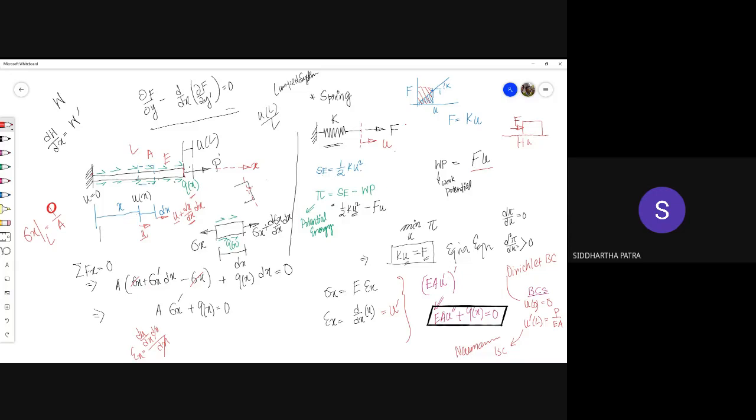When we are dealing with statically indeterminate sort of problems, okay, we'll have to write down all the equilibrium equations, but then we cannot solve them because the problem is statically indeterminate, which means literally that you cannot solve it from the equilibrium equation. And then we would write all the expressions for stresses, strains, and displacement, and then all of these equations will have to be solved simultaneously, sort of a huge set of linear equations.